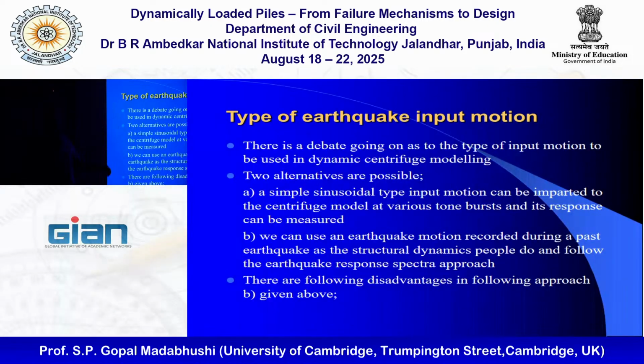Whereas if you put in sinusoidal motion, it is all quite clean and you can track it if the natural frequency of the soil is changing. So both are true, and many people, even with sophisticated shaking tables, still use sinusoidal motions where you want to study the fundamental behavior.